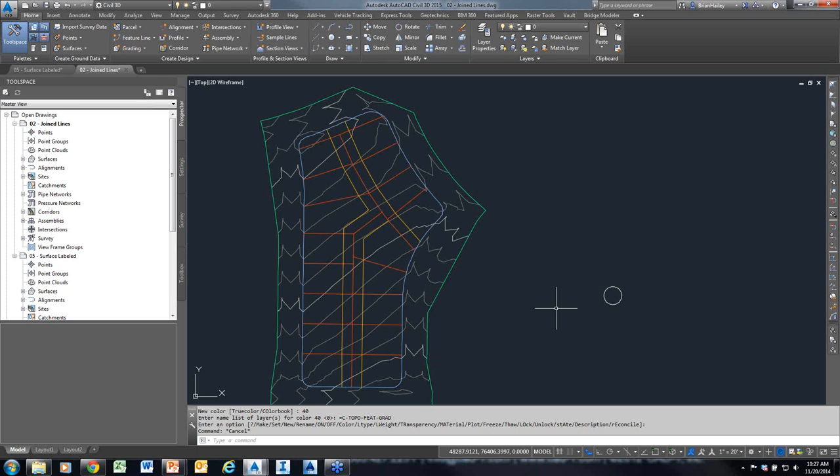Another question came in. When you use feature line styles, doesn't it give some kind of priority on which feature line wins? Yeah, and that's what I was just talking about, Joe. You typed that in just as I was talking about it. As I said before, in my opinion, it should not ever come into play because you should always have vertices whenever your feature lines cross.